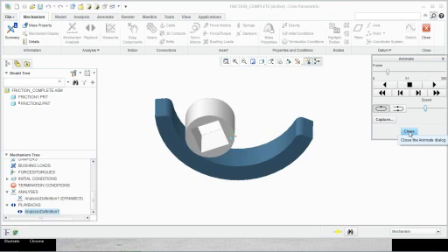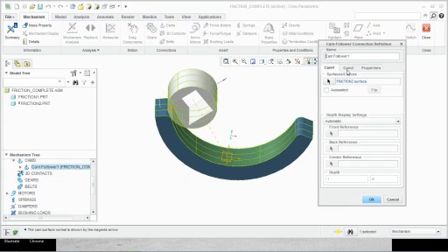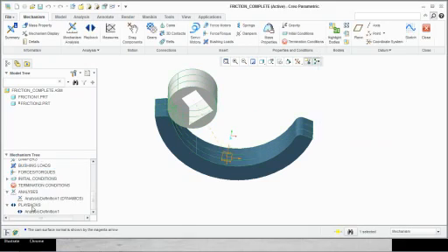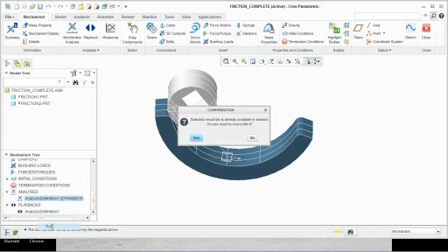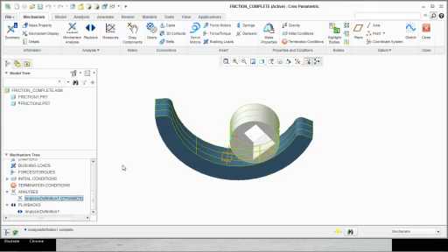Now, similarly, we can play with the parameters and say the coefficient of restitution is 0.5, friction is 0.5 and 0.3. Notice that static friction needs to be always greater than the kinematic friction. So let's go ahead and run this. You can see that because the coefficient of restitution has increased, it dies down fast.